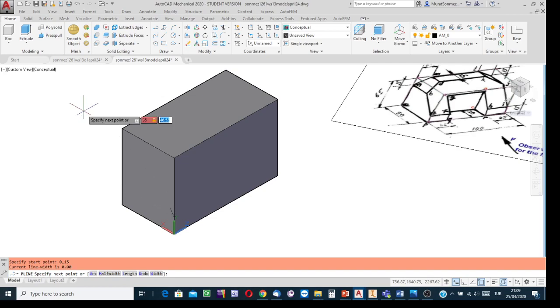Click on the comma key. The other value, delta y. Delta y is 65 minus 15. 15 is the location y value, the location dimension for the starting point, the first terminal point. So relative to that point, the coordinate of the ending point is 65 minus 15. It makes 50. Write 50. Positive, because the point is at the positive side of the y-axis, delta y is positive. Write 50 and then press enter.